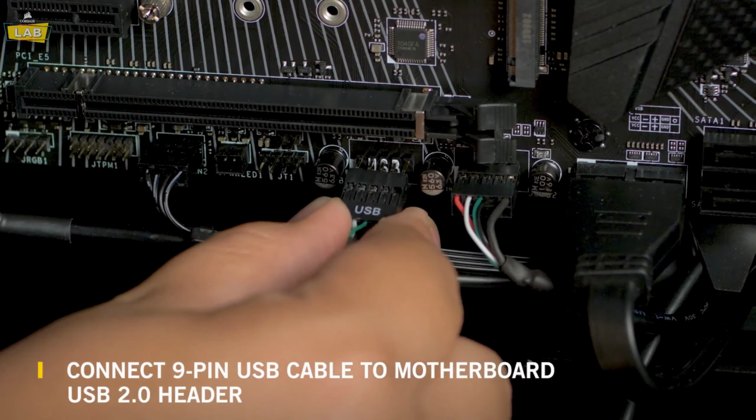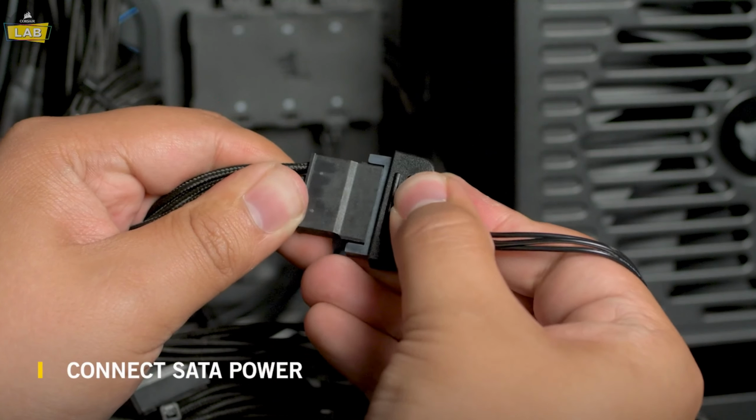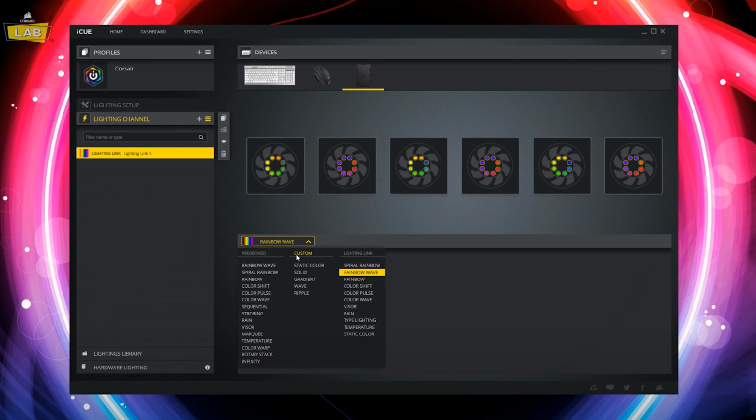Plug the 9-pin USB cable from the Lighting Node Core into an available internal USB 2 header on your motherboard. Then connect your Lighting Node Core to SATA power. Finally, download Corsair iCUE and set up your Lighting Node Core with the appropriate fan type. And that's it! The Corsair Lighting Node Core makes setting up iCUE-compatible RGB fans easier than ever.